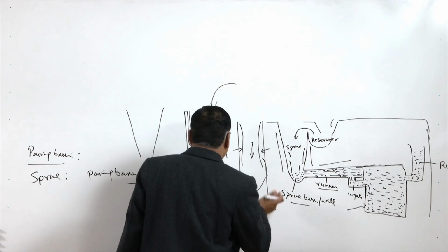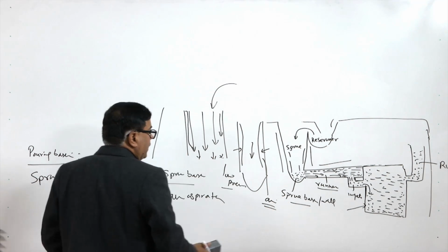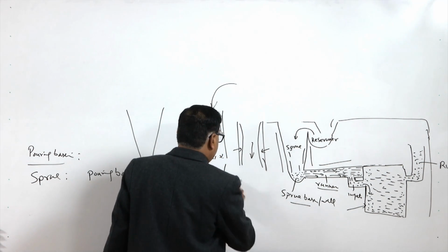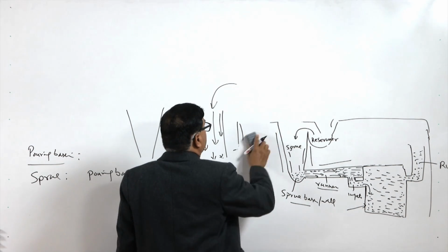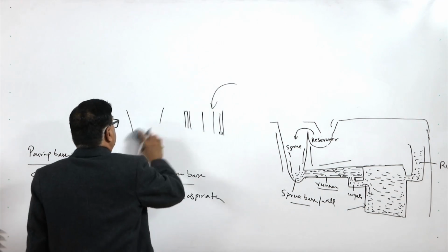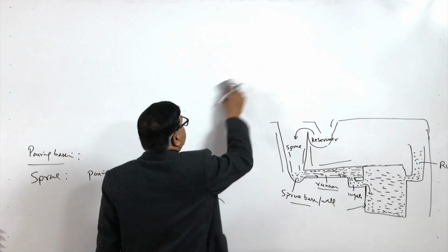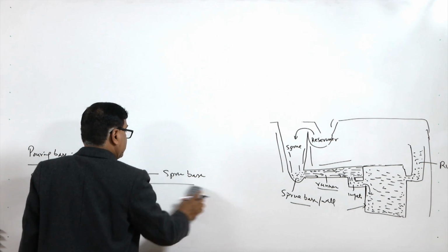This leads to the mixing of air pockets and a lot of dissolved air with the molten metal, which increases the tendency for gaseous defects in the casting.